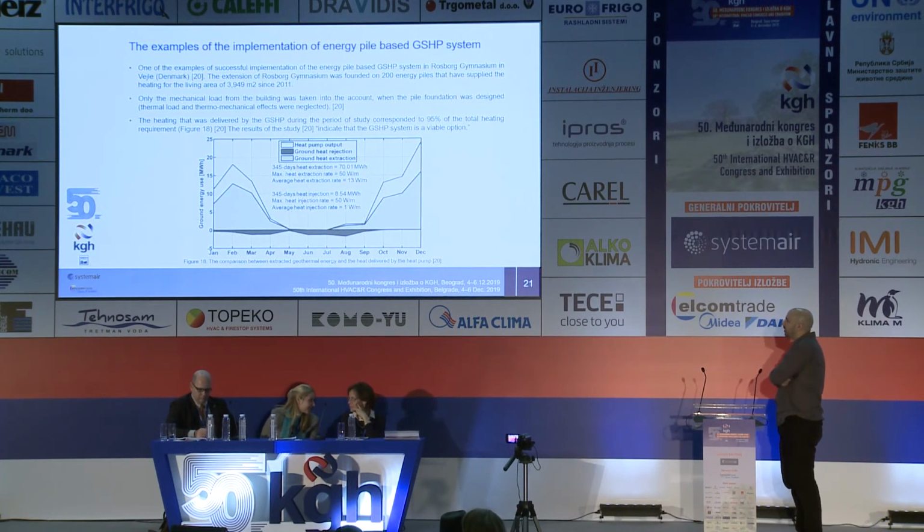The flaw in the design, if I can say so, was that when the piles were designed, only the mechanical load from the building was taken into account, which is a mistake, and you could see in previous slides that it is really important to incorporate cyclic temperature load in your equation.